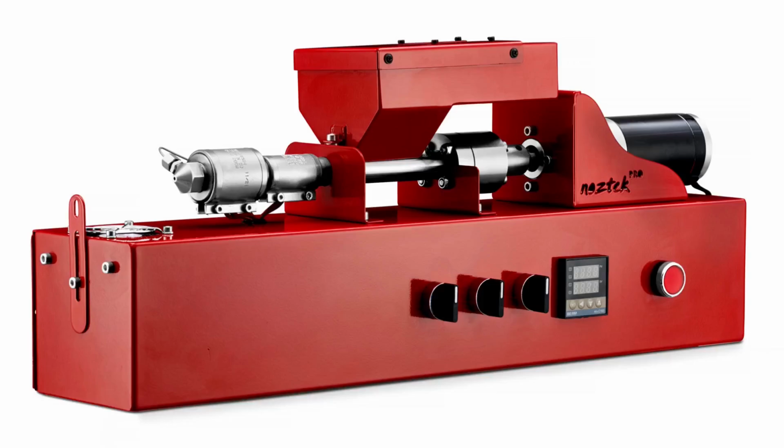I've been talking about what is 4D printing and what are the materials needed. Now let's look into one of the two most important machines needed to fabricate this 4D product, which will be an extruder. This image over here is a Noztek Pro desktop extruder. And like I mentioned, the materials earlier, which is the thermoplastic polymer and the iron powder, will be dropped into the hopper of this machine, which will then produce the filament needed.